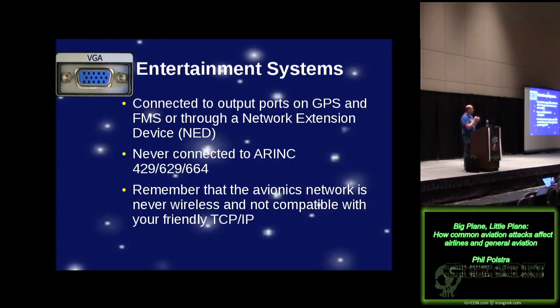That connection is programmed so that port 2 can only receive from a certain number of ports, and port 2 can only transmit to another set of ports, right? So you have a lot of restrictions. So every single connection in that switch has to be explicitly programmed, right? It's not like, oh, I can just start sending fake packets around this avionics network and things will happen. Well, it's a lot more complicated than that, right?